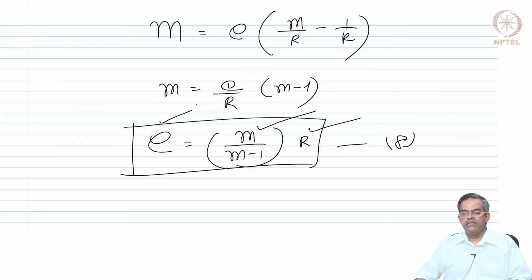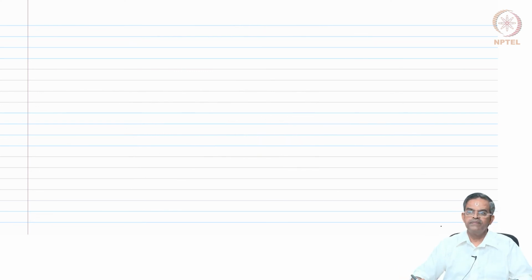Friends, it is very interesting. Now, the shift of neutral axis also becomes part of the geometric property, whereas m is a modified area. Okay? m is a modified area, or modification in the area, because of capital M applied on the curved beam, and E has also now become a geometric property. Okay? Having said this,